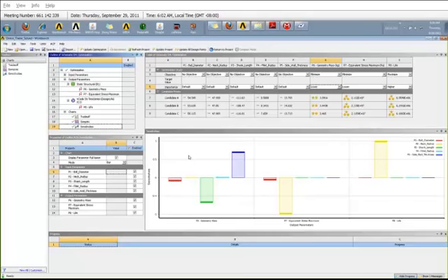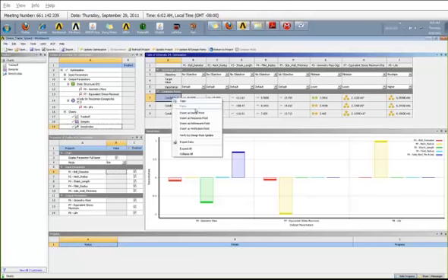Once you're done with the optimization study, one final thing that you should do is, again, this is a predicted value based on the response surface. This is not a calculated value. So the one final step you should do is right-click on the candidate that is appropriate for you and choose insert as verification point or insert as design point update, where it will insert this particular point with these input parameters as a design point and solve it once, and you can compare the predicted and the calculated value. If your response surface has a good fit, these two values should be very close.